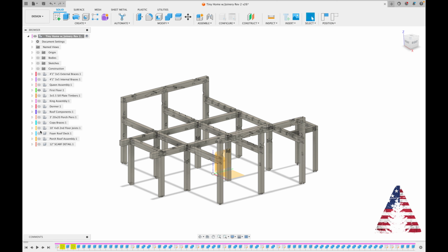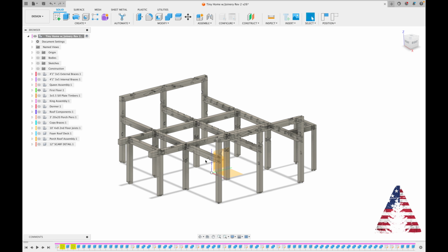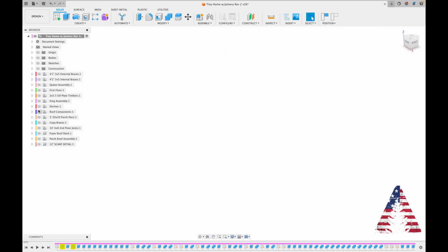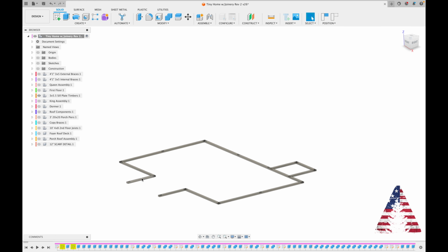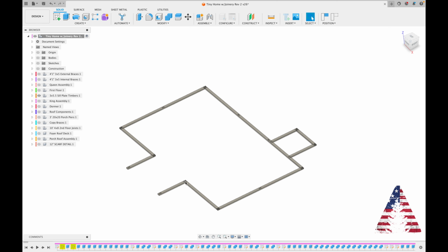Then we can start here. And this is where, before we get started with this, we'd have to set down the sill timbers. So sill plate timbers are all black locust, and the frame is integral, right? So these little squares here are mortise pockets and tenons on the bottom of our main first floor posts. I'll tie into that. Mechanical room here, those are all tenoned into mortise pockets here on this sill timber.